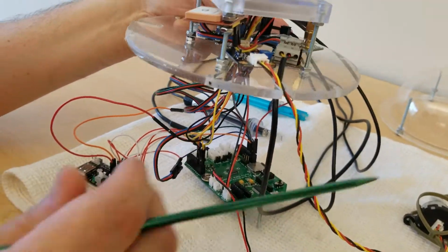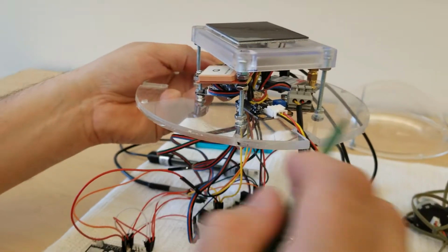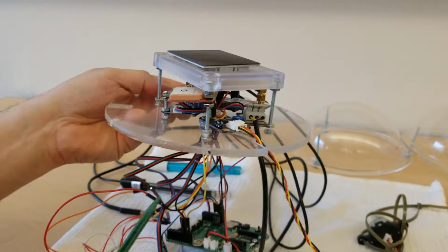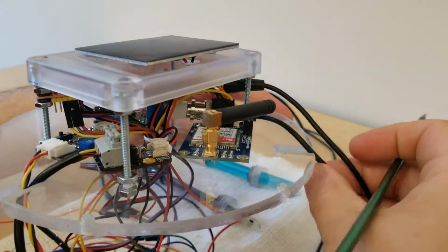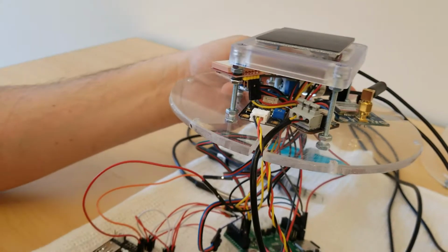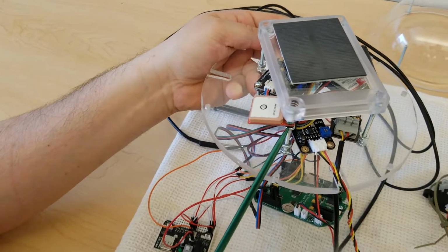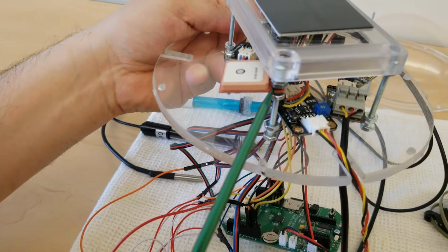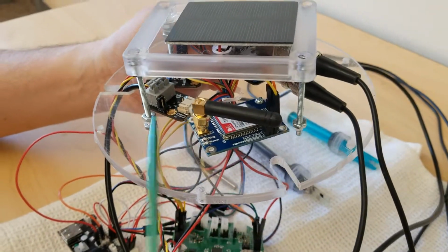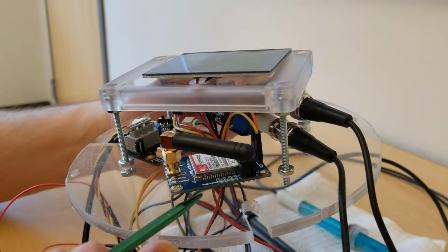We follow it up through this polycarbonate disc. We can see all these shields for each individual sensor that leads in, processes the data, and then leads down, plugs into there. So we've got pH and electrical conductivity here, temperature here, and right here we've got the turbidity. Furthermore, we have our GPS board and antenna, which gives us our location of the device. And then coming around this side, you'll see this antenna. This board here is our SIM900 modem, which handles our GSM signal going to our cellular network.